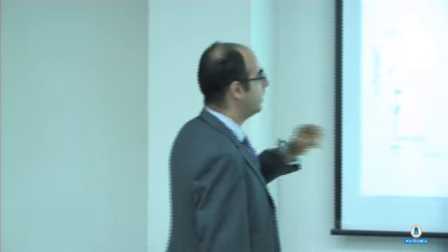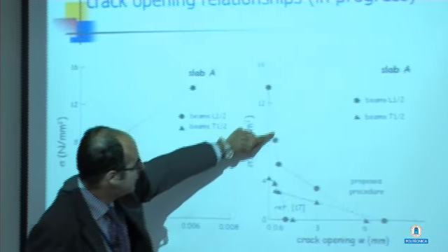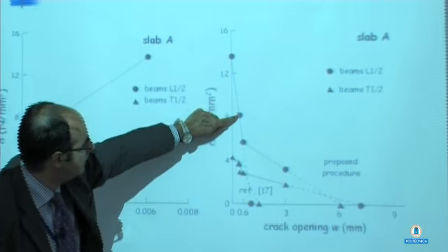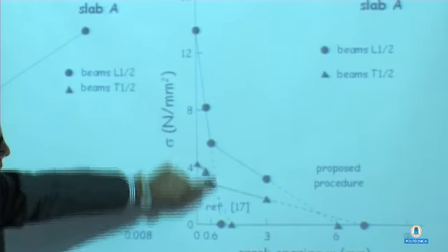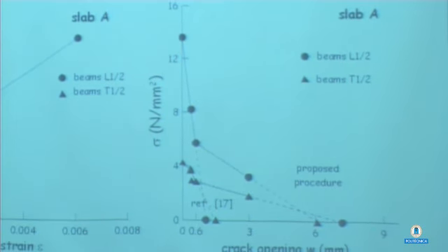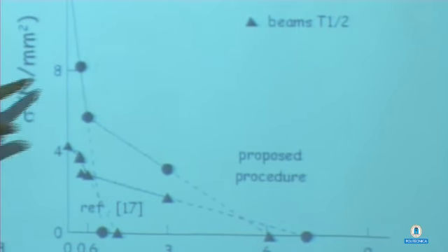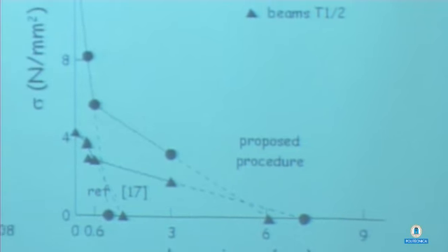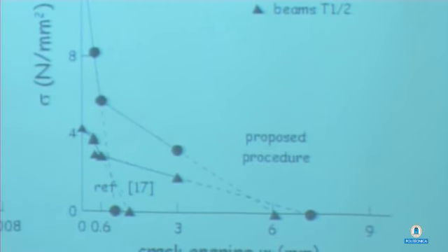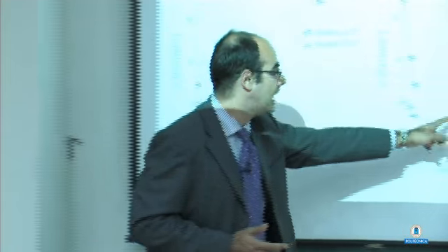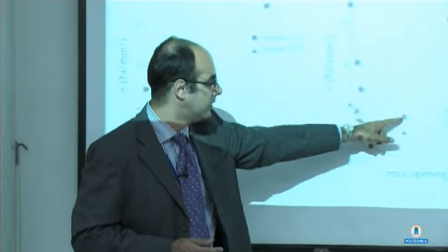And if you go with this kind of identification rule, you see that you get this very steep decrease. This is the peak, this is the serviceability limit state, this is the ultimate limit state, and if you extrapolate this, you go rapidly to 0. Even if we didn't perform the inverse analysis, you can easily imagine that this is not good for the performance that we got. So we proposed a much more, not cumbersome, but with some other points, not limited to 2% of the specimen depth, but up to 10% of the specimen depth, just to add a further point.